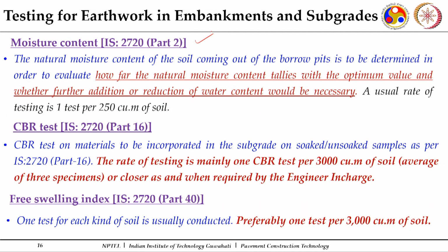Moisture content, as I said, is important for compaction also. Because we prepared trial stretches, we worked out that at this moisture content, this much compactive effort will give you the required density. So, during the construction itself, not only after one layer or course has been constructed, you can keep on making these checks. Whosoever is there, whether the engineer from the contractor side or from the consultant side, will look into these things to ensure them.